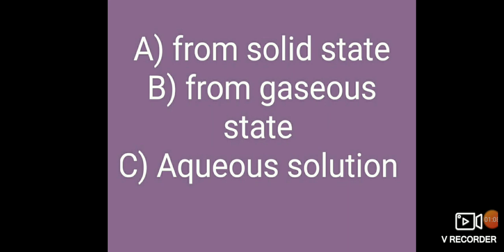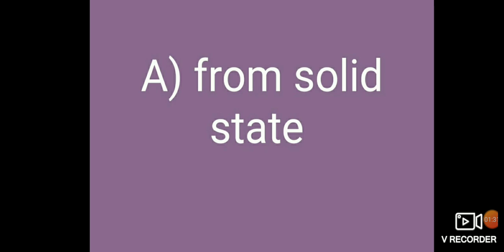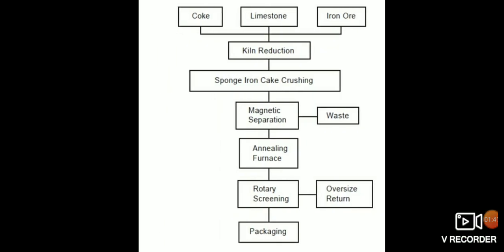This is a batch process in which the ground ore does not move during reduction but is static, in contrast to other direct reduction processes which are continuous. The Hoganas process is based on the use of quite pure magnetite ores. The iron ore is reduced with a carbonaceous material. The figure shows the steps involved in producing such powder.